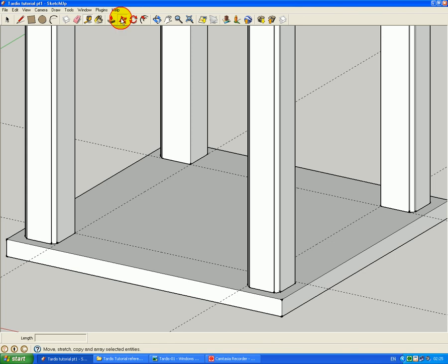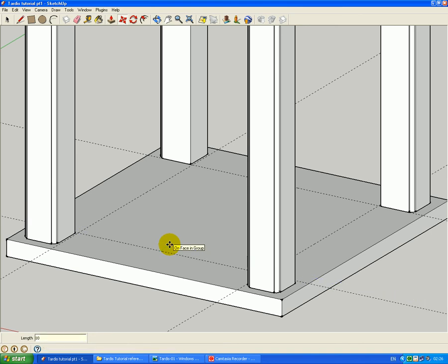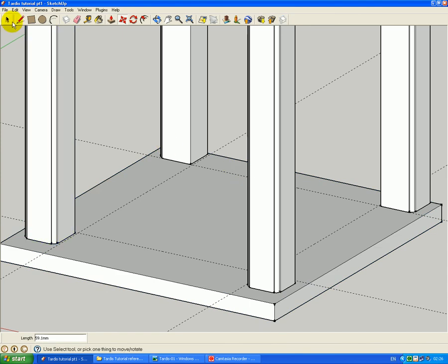It's only a few millimeters out, but we need to move these guides along the red axis here 10 millimeters, and the same again, 10. Move this one 10 and move this one. Let's undo that because it's moving the base. Edit, undo.